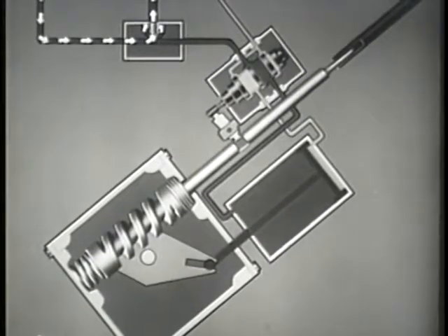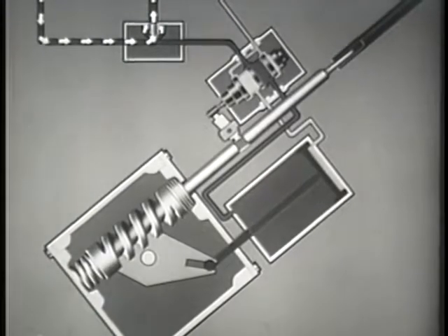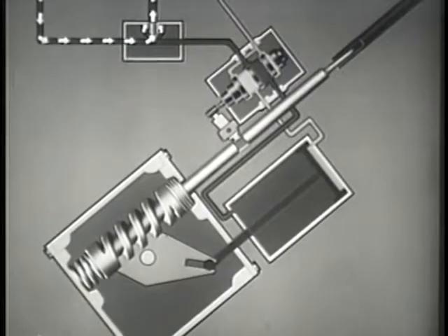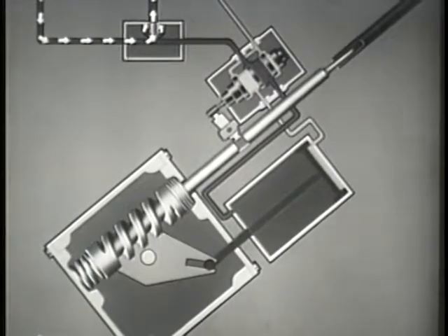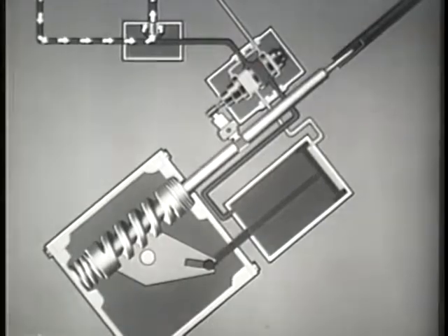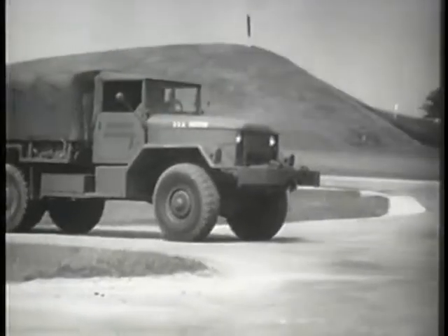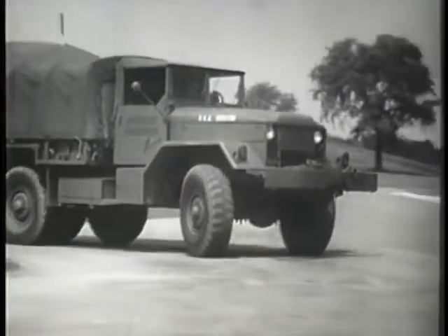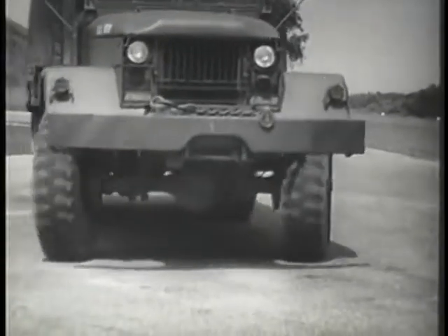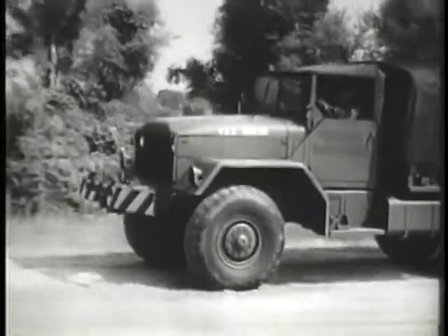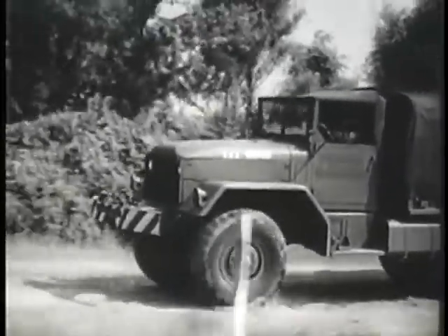When the piston reaches the end of travel in the power cylinder, the pump continues to deliver fluid, causing an increase in operating pressure. The relief valve provides an escape for this excess pressure back to the reservoir. After completing a turn, the driver releases tension on the steering wheel, and the steering system is returned to straight-ahead position by the steering geometry of the front wheels, allowing the hydraulic system to return to the neutral position.